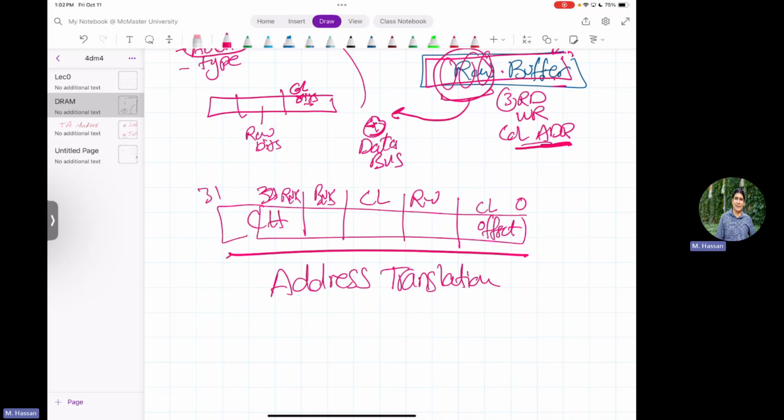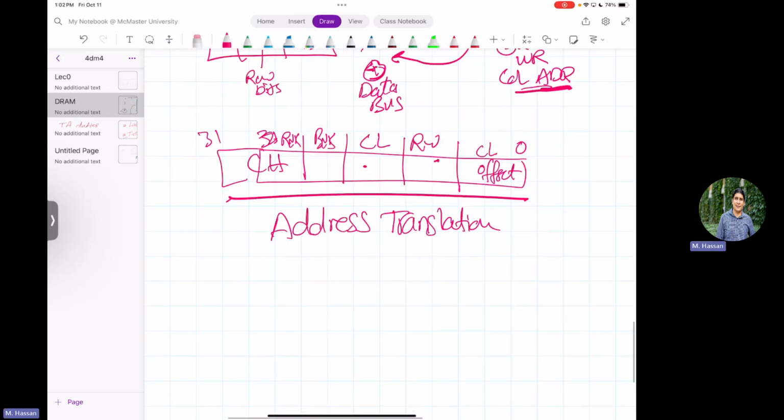If I do my set, where does my set really reside? Is it within the column bits of the DRAM, within the row bits? What is better in terms of performance? Some co-design between different levels gives you good performance. But basically, you do an address translation from the physical address to the DRAM low-level segments.